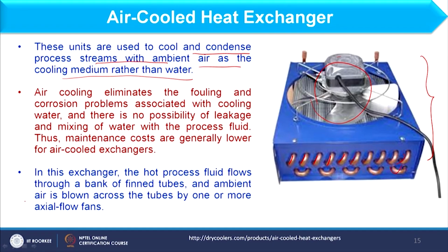So in this air cooled heat exchanger, if I am putting the fan at the top, which means before the process is going on, because once air is thrown by this fan, then condensation will take place. This type of placement of fan we call an FD fan or forced draft fan, because it forces the air in the system. It means it creates positive pressure in the system.